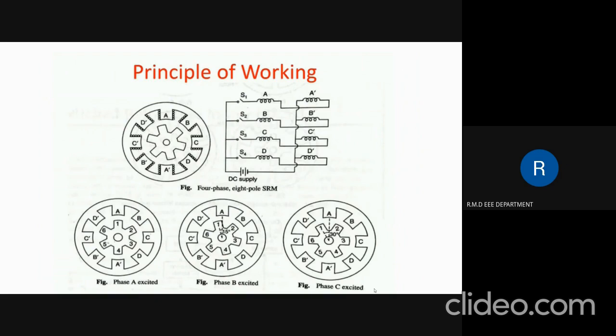Now when the load torque is increased, the speed of the motor tends to fall so that the power balance is maintained. If the speed is to be maintained at the same value, the developed torque is to be increased by increasing the current. Thus more power is drawn from the mains. Thus electrical to mechanical conversion takes place.